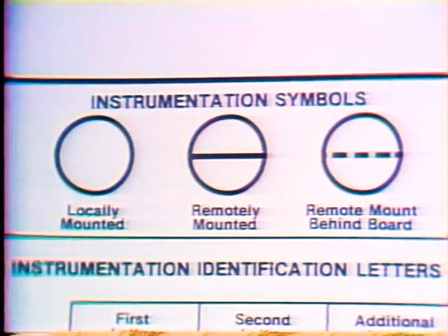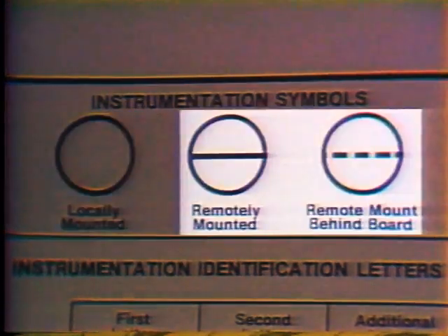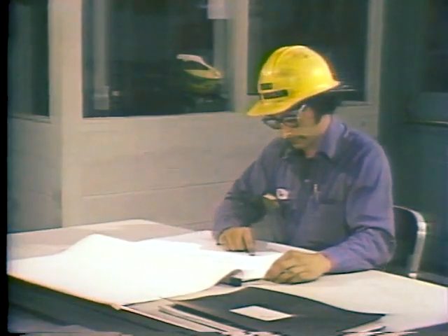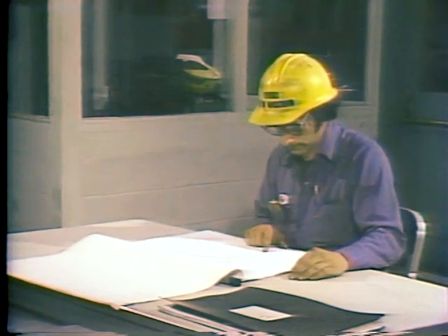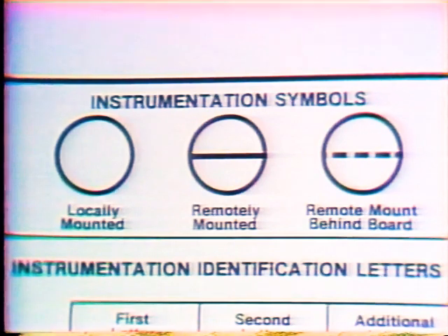In the system we're going to use, remember, your plant symbols may be different. The instrumentation symbols look like this. A plain circle indicates a locally mounted instrument. A circle with a horizontal line through it means that the instrument is remote. Now, while symbol systems and legends vary, in most cases a standard system is used for all P&IDs in a plant. For our purposes, throughout the remainder of this unit, we'll use this system to indicate instrumentation symbols.